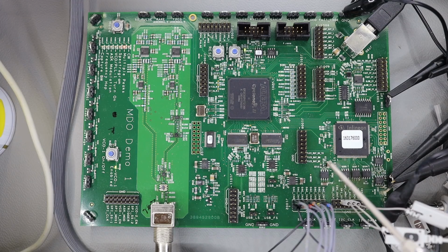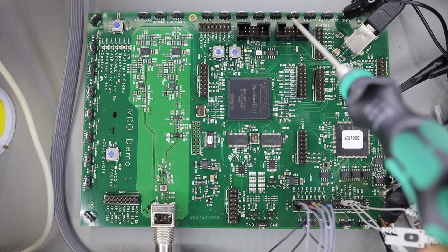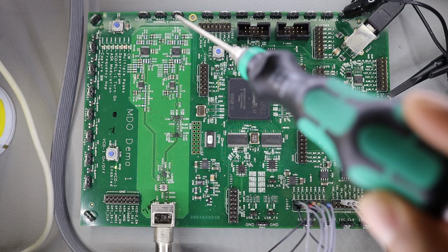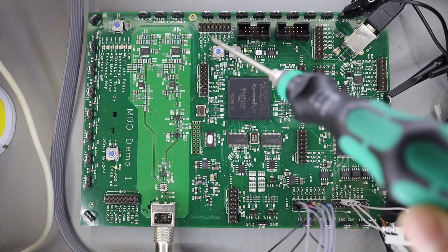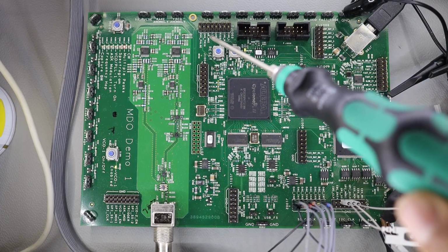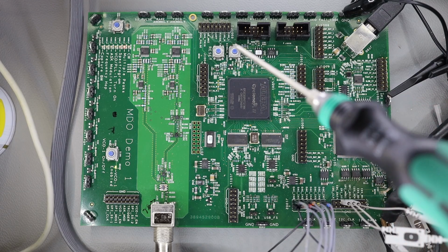So what else do we have? We have flex connections, FlexRay, RX and TX, and on this side you have fast edge, AM modulation, CAN, RS232, UART, LIN, frequent anomaly, rare anomaly, and SS pulse. You also have some of these signals available on this header, and there is also a 40 MHz clock, 2 nanosecond trigger, and 2 nanosecond pulse.